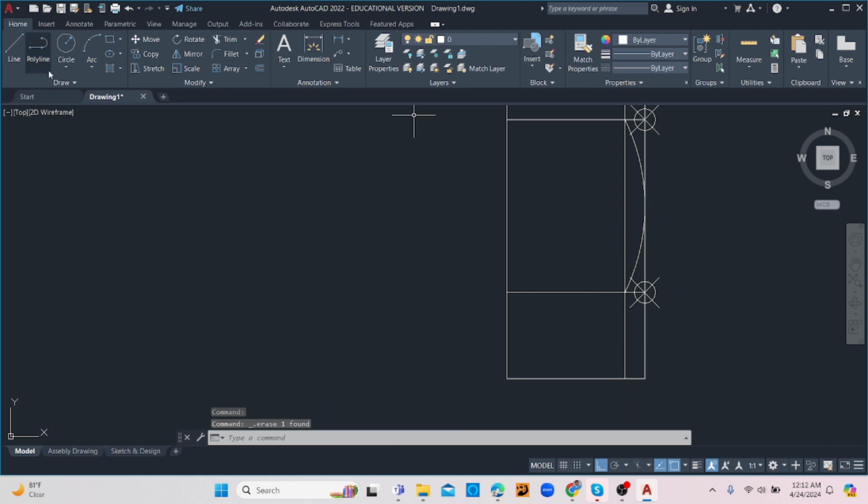Once that is in place, I now need to draw a curve here and here, but in order to do the 3-point curve, you'll have to have 3 points. So I'm drawing a line from here to here, that's this line here. So I'll have something to snap to. So I'm going to go arc from here, midpoint, and back down. And then now with this curve, I can easily mirror this curve to the other side.